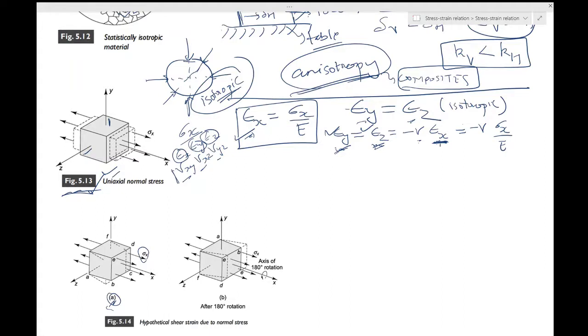Now if there is a shear strain present, then there has to be a rotation in this element, and that is shown by these dashed lines over there. If you recall, if this was your original O, C and E, you would call it a shear strain when this would move to O dash, this would move to E dash, and this would move to C dash.